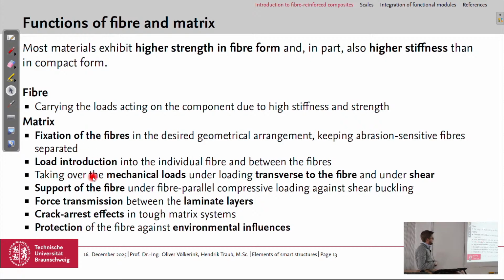They serve as a load introduction into the fiber. So you have to bring the loads into the structure, which is done also by the matrix. And they take over the mechanical loads when you have loads transverse to the fiber, so not in fiber direction but perpendicular to it. Then the matrix also carries load, as well as under shear. And under compression, they prevent the fibers from buckling, from having a stability failure of the fibers.